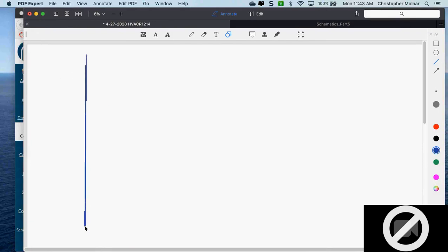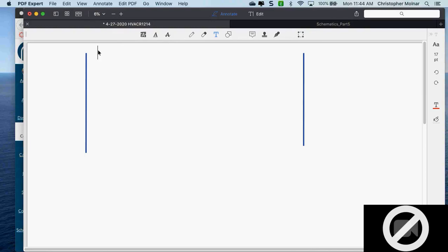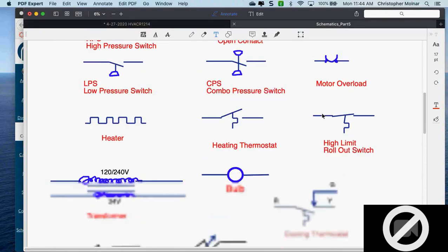What are we going to be seeing as our basic oil burner parts, as our basic electrical parts on our schematics? Let me make these a little bit shorter. We always start any schematic with our two sidebars of our ladder rung, because we're talking ladder diagram. We have our loads all here. So we're talking line and neutral. Get in a habit of labeling as you go.